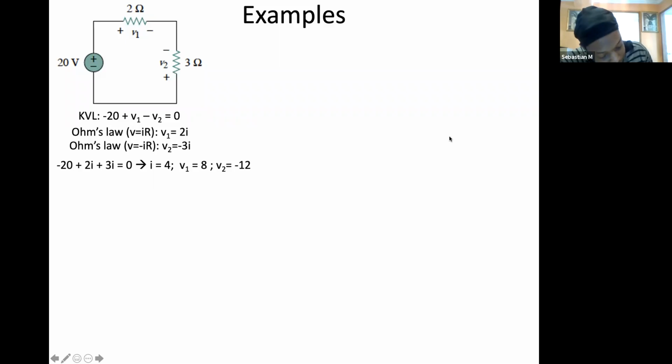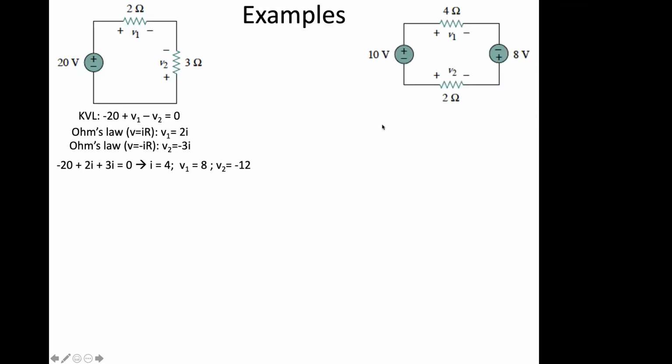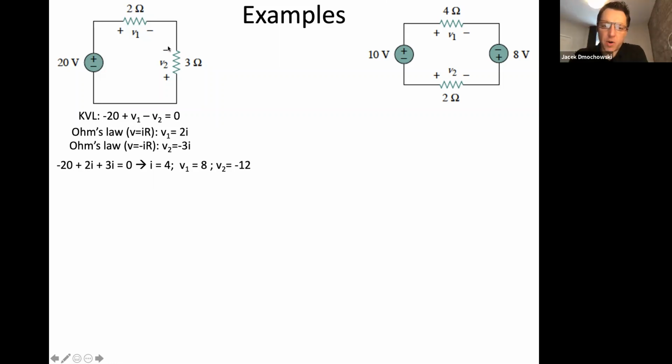Thank you. Okay, awesome. Professor, I have a quick question. Go ahead. When you first do Kirchhoff's law, you're already taking into consideration that V2 is in the other polarity, correct? Yes. So you're doing it again in Ohm's law? Yeah, you keep that polarity, because the polarity of V2 has to be the same for both equations. Otherwise it's like two different variables. Okay, thank you. It's a good question. The polarity has to stay fixed throughout the problem.